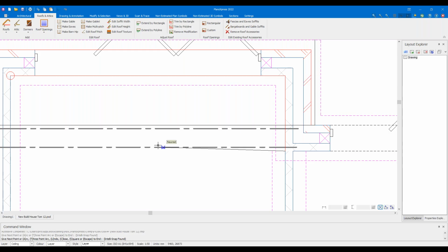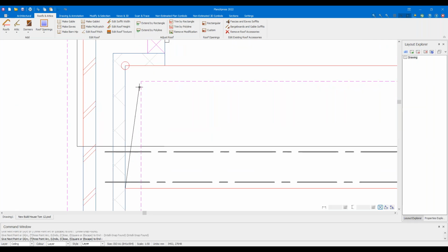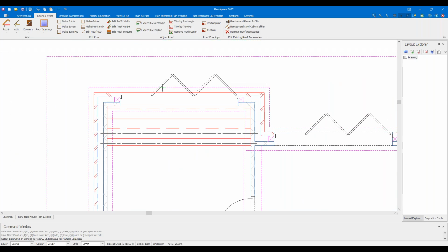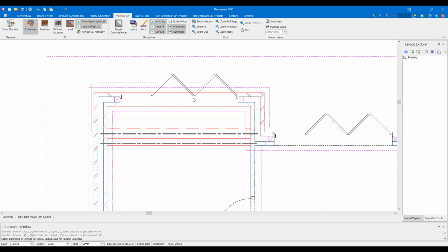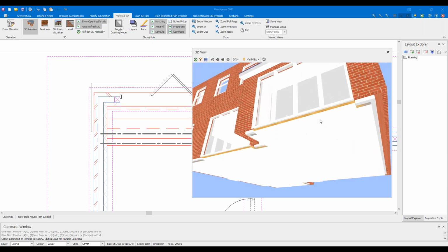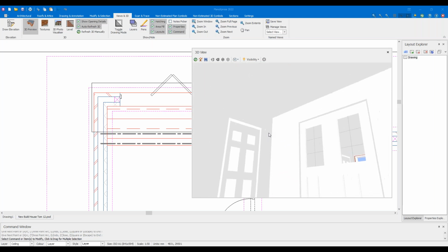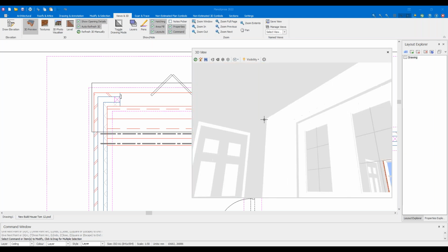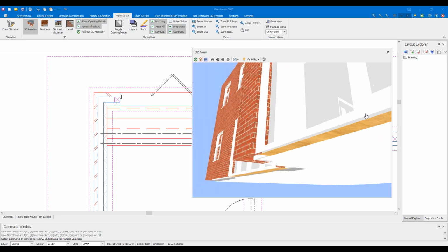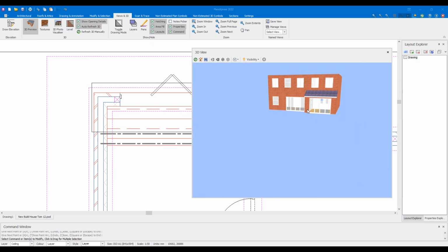And I look at my 3D. Take that across to the left, perpendicular snapping point, and then take that up and just press C to close. So I've got a section of ceiling drawn in. To look at my 3D preview, my ceiling's nice and consistent all the way through.